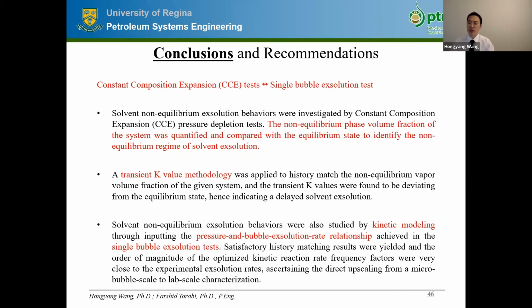So the last part is the conclusion and recommendation. For conclusions, we have conducted the CCE tests compared with a single bubble exsolution test. And we have found that the non-equilibrium phase volume fraction of the system was quantified and compared with the equilibrium state to identify the non-equilibrium regime of solvent exsolution.